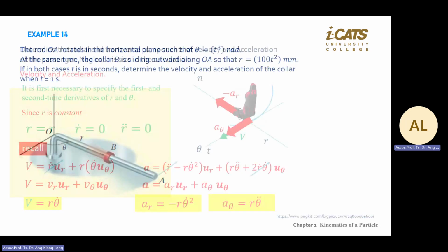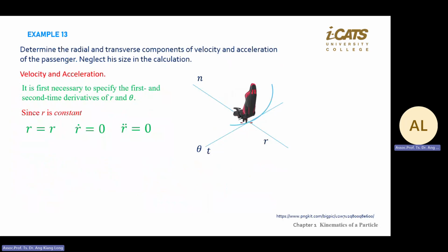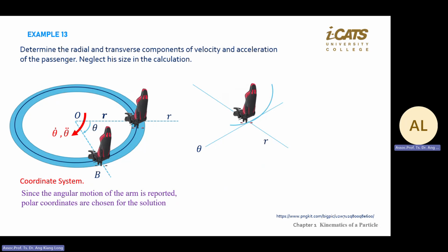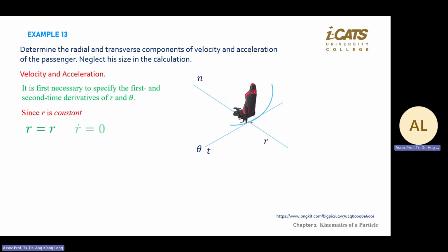Yeah. So I repeat one more time. The steps for cylindrical are to draw the axis first. First, draw the R positive direction. Draw the angle axis, the direction of turning, label theta dot, theta double dot, and then focus on the object. Put in the tangent and normal directions. Once you have that, you call out these 4 equations.